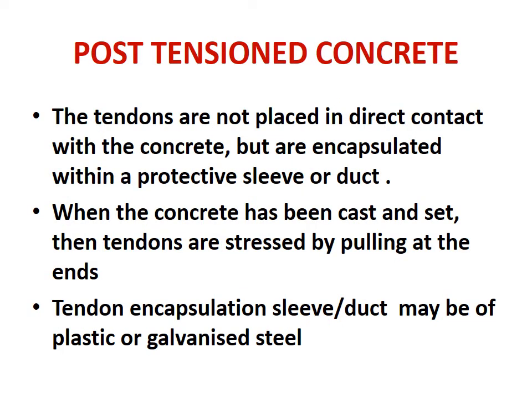In post-tension concrete, the tendons are not placed in direct contact with the concrete, but we provide a sleeve or duct. Inside the sleeve or duct, the tendons are placed, or they are encapsulated, and when concrete has been cast and set, the tendons are stressed by pulling at the end. The sleeves and ducts encapsulating the tendons may be of plastic or galvanized steel or similar material.